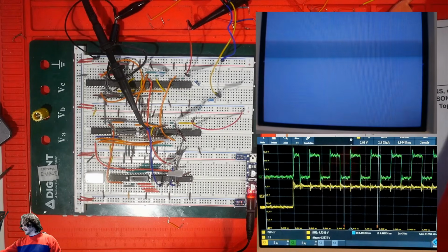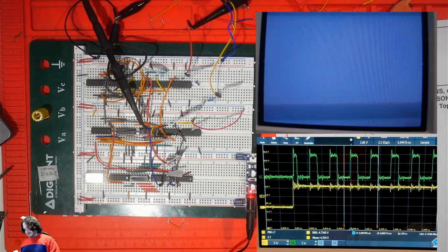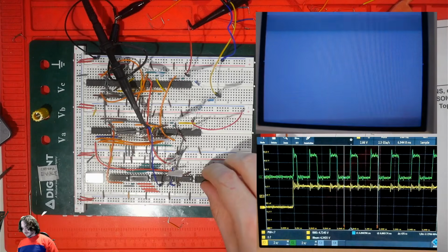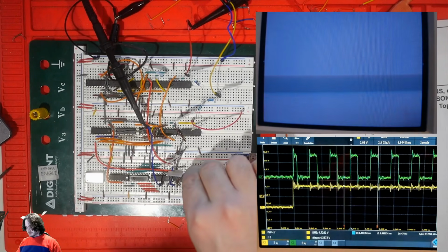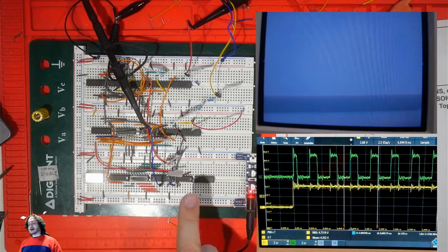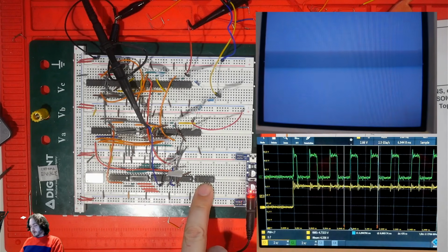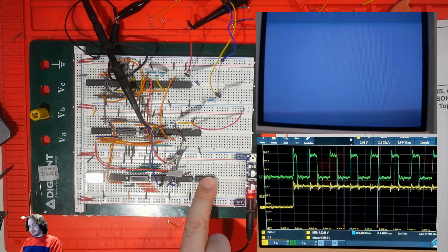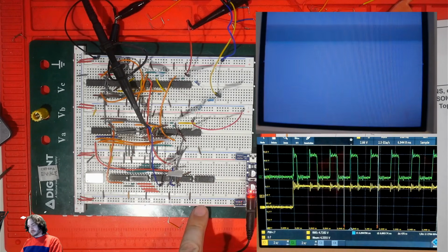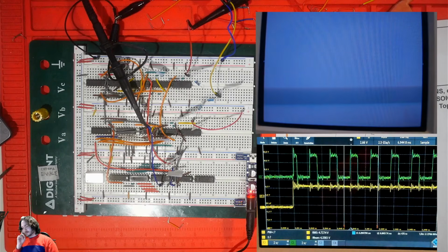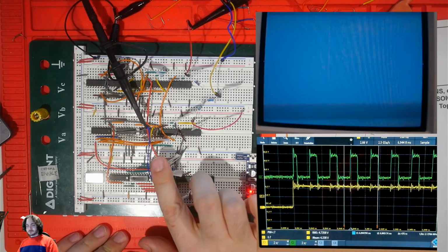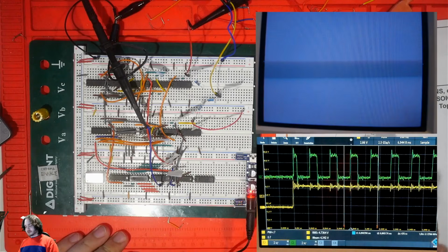So the final chip that's required to make this work is a 74HC257, which is another selector like the 151, but instead of selecting one of 8 inputs to go to one output, it selects one each of 4 pairs of inputs to go to 4 outputs with one shared selection bit, which is ideal. We have 3 bits that we want to control at once, and then during a certain time flip them to a specific value and let other values through other times.